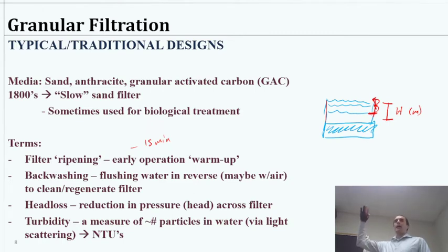Either the height of the bed, we're going to overflow our beds, which we would never let that happen, or more likely, our concern would be if we give it too much pressure, at some point, we start getting concerned that the sand grains will just split apart, or we will channelize them, forcing too much water or pushing too hard. The sand will give way structurally, and then you'll just have a channel or a fissure, and all our contaminants will go through.